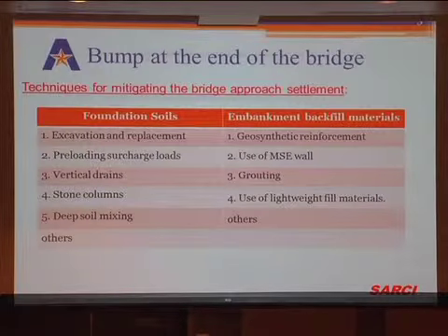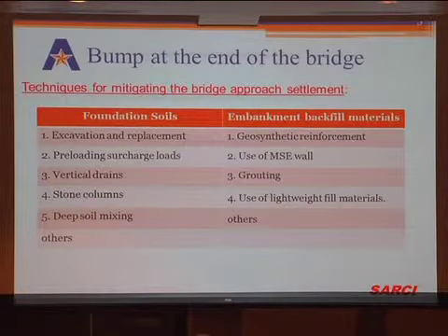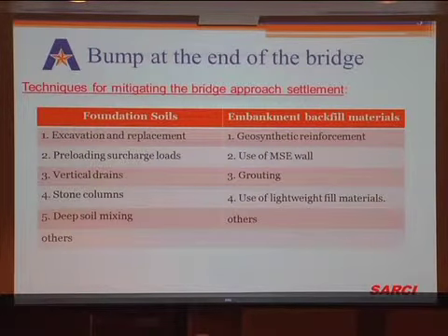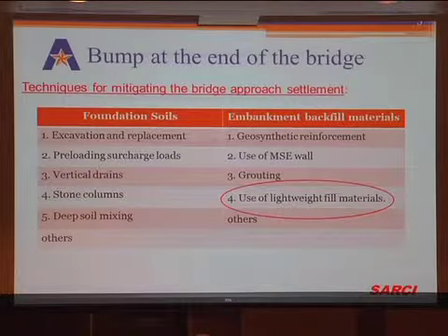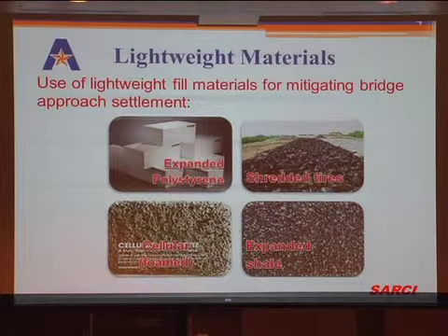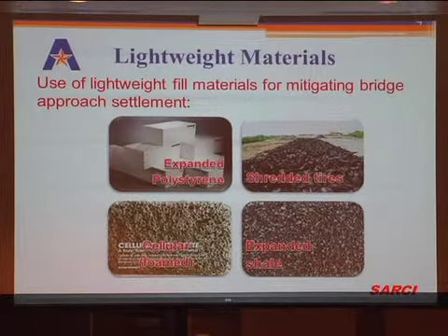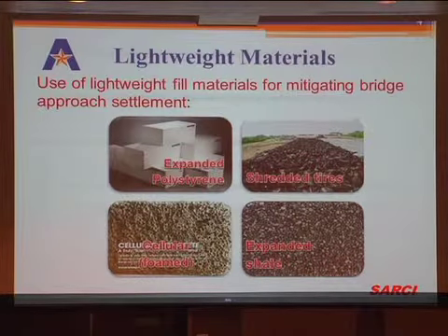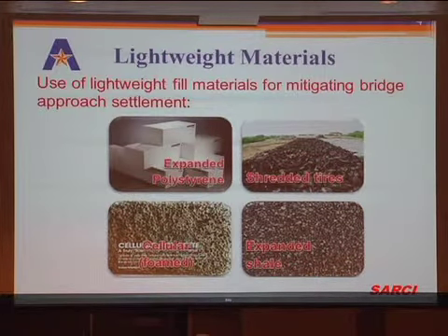Again, you can also do grouting, which in this particular example I'm going to present, we tried micro grouting, and it didn't help much. And the other popular one is the lightweight fill material. And that's the one I'm going to focus on more today in my presentation, lightweight fill embankment material. Here are the 4 types of embankment fill materials you have here. You have expanded polystyrene, which is your EPS material. That's the one I'm going to be presenting today.